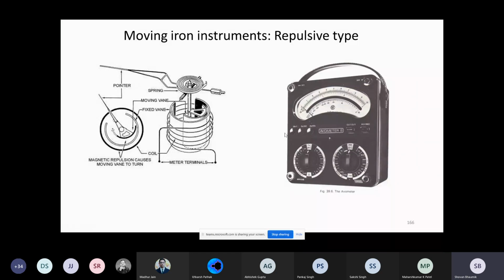Another thing I want to say, in the top one you see 0, 1, 2, 3, 4, 5, 6, 7, 8, 9, 10. This is a uniform scale, but in the bottom one, the scale is not uniform. 0, 10, 20. You just note this. Now I will not explain, later we'll explain. But the scale on the top is the voltage or the current, and the one below is the resistance.